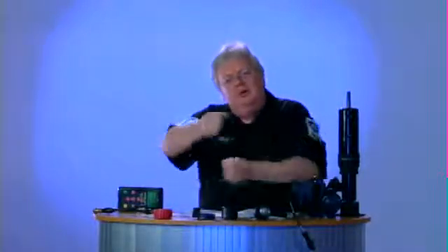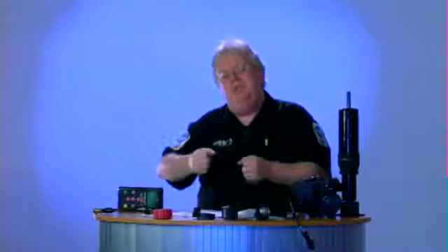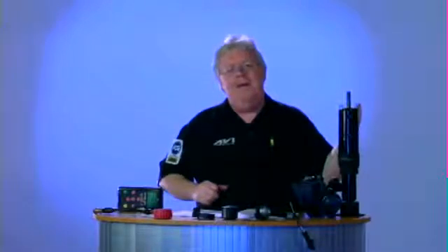On the other hand, if you only hear the squealing of a slipping belt when you turn the steering wheel or turn it almost to lock position, that's extra pressure from the pump binding up, causing the pressure to go up and the amount of work it takes to turn that pulley to go up.